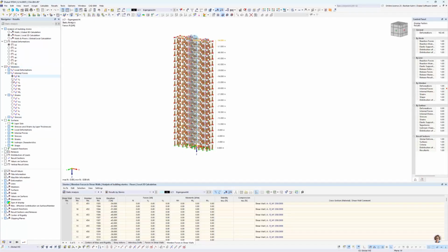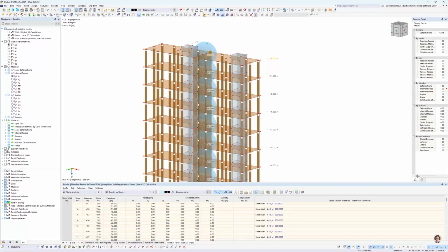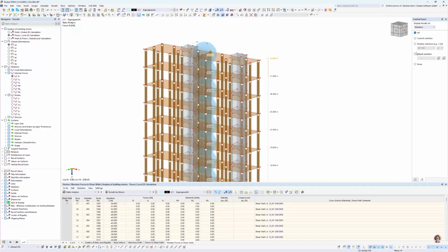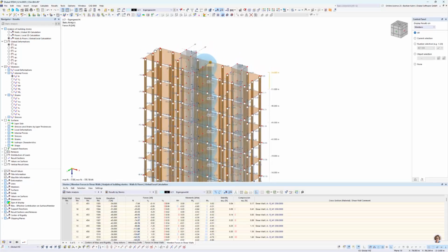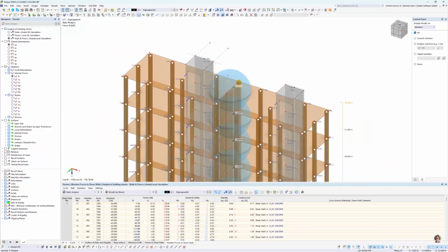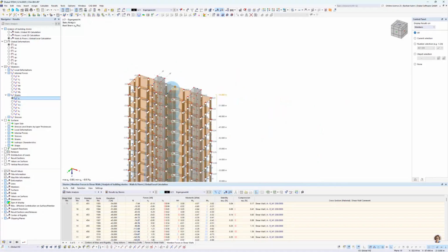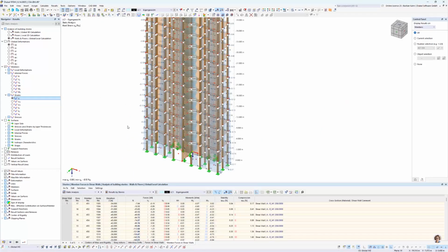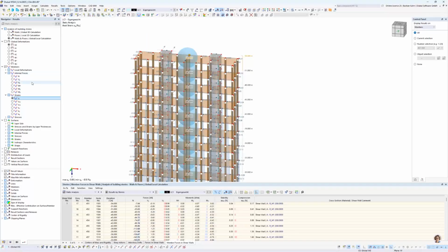And when we take a look at the normal force right now, and then of course go to walls and floors, you can see that here we have near 30 kilonewton, which is something that I would have expected. The value that I had there before was just wrong. And why was this wrong? Because the strain of it was also wrong. When we look for the strain right now, you see that it's just much better harmonized.